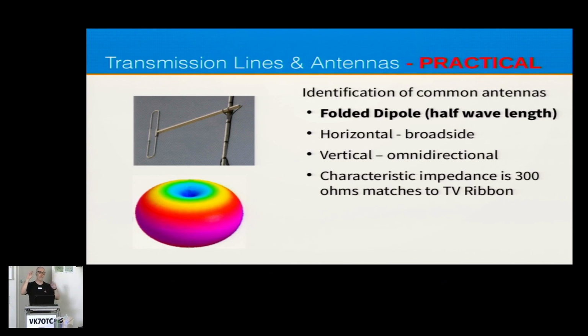These are very popular commercial antennas, and you'll see these in all sorts of orientations. You'll see one that's horizontal, one that's vertical, one that's at 45 degrees, and it's a very good way of cutting down or reducing the interference from other services on that site. So you'll see these in all sorts of orientations. If they are in that sort of orientation on the picture, it's an omnidirectional orientation. It's the donut flat on its side, on its face.